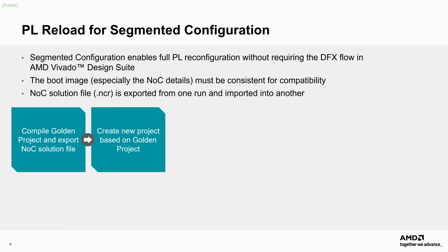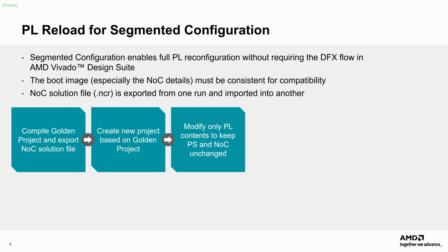NOC connectivity. If designers expect to modify the NOC usage within the PL domain, either entirely in the PL domain or the PL NMUs connecting to the PS NSUs, it is advised to separate this dynamic portion of the NOC into one or more unique NOC IP instances. This allows the PS NOC to more easily remain untouched from one run or project to the next.